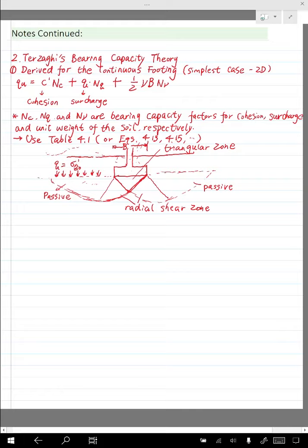To calculate this Q or sigma Z0 prime, we need to see what soil layer or layers are above this line. If there's only one layer with a unit weight of gamma, then it's just gamma times D. But if there are multiple layers, we need to do it layer by layer using the theory that we learned for the stresses in the ground.